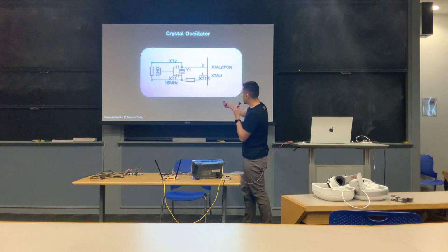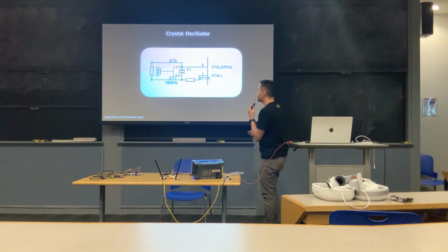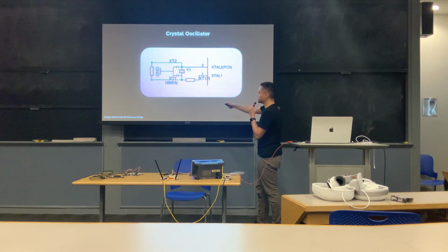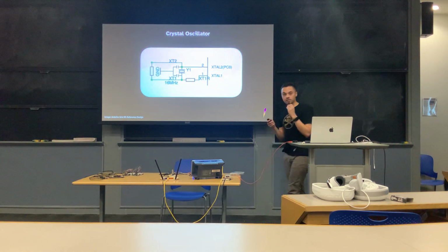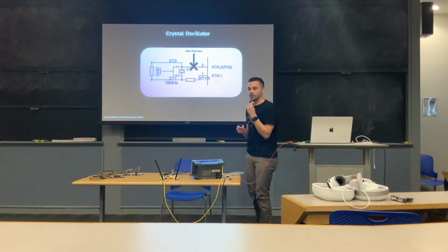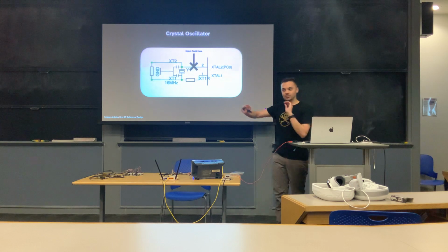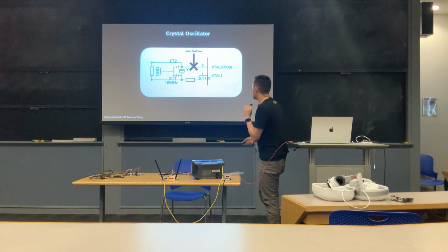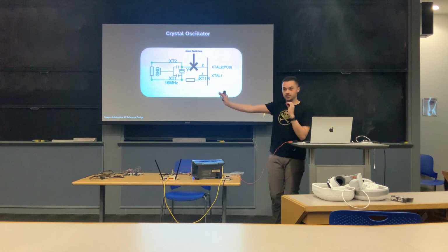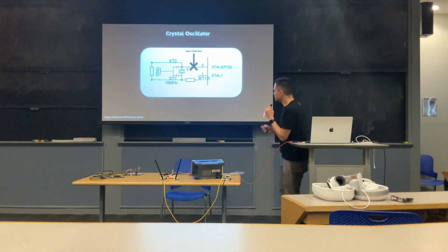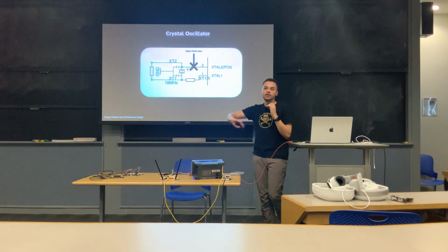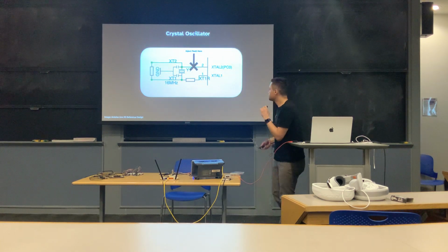So how does it actually look on the circuit? This is the input to the Arduino. This is actually from the reference design. We have that crystal right here, and those two capacitors that load the crystal down to ground right here. And what we're going to do is attach a wire to this point of the chip, which you're not supposed to do. This is a very bad thing, but we're doing bad things, so this is actually good. And what we're going to do is very momentarily short that pin out completely to ground through a transistor. And we're going to do it in a way that's been pre-profiled so that we don't completely kill the chip, but we just bring it into this weird condition.